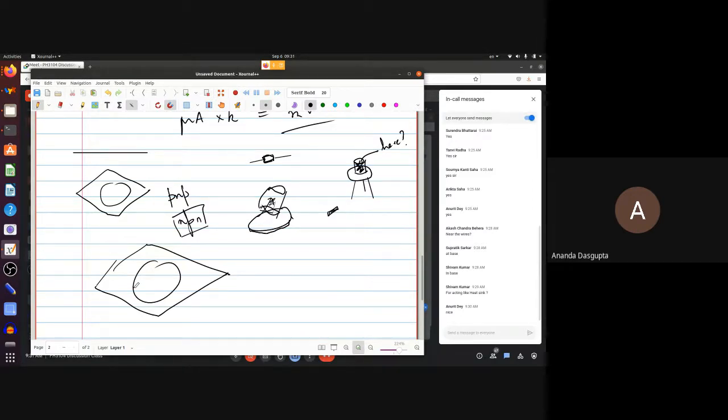That diamond-shaped thing with the round-shaped thing is also a transistor. It's a power transistor, something which carries a lot of power. And there also, the actual transistor is really this big. This huge thing, the much bigger thing, is really there to provide a much bigger surface area. And why? How does it help? It helps by allowing heat to flow away.